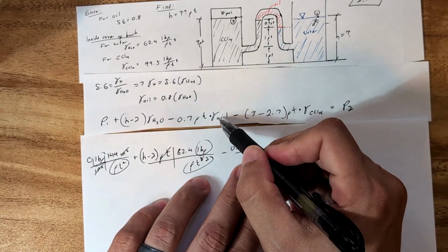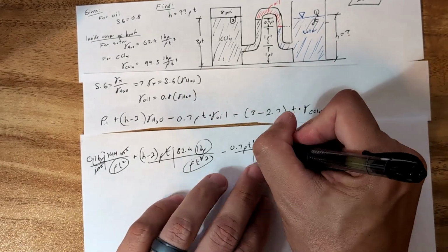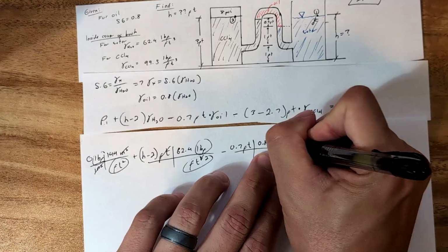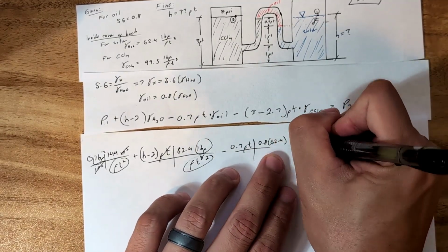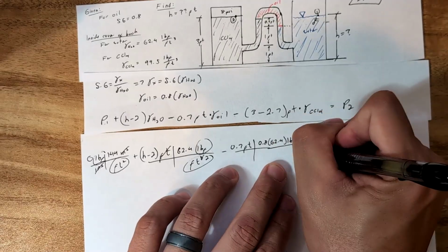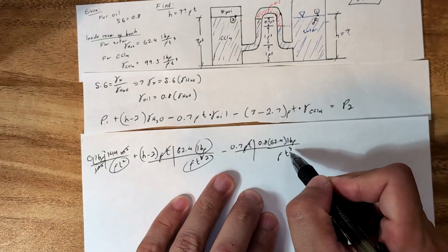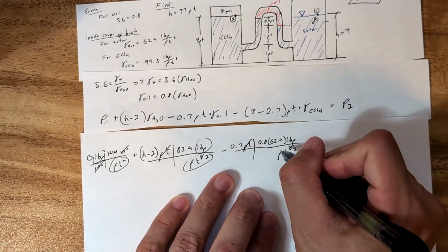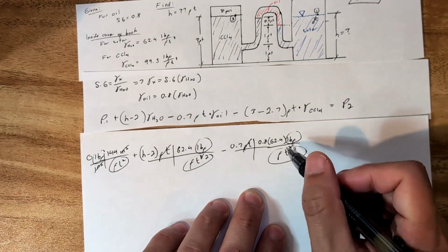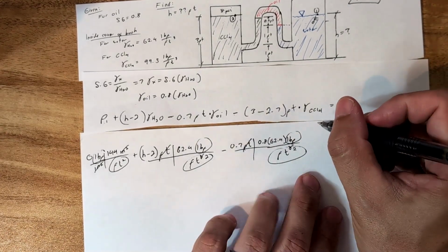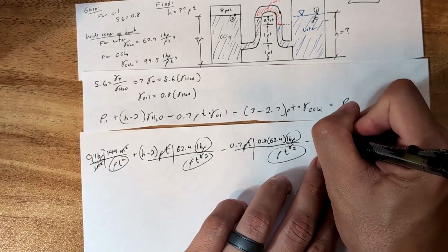And then for oil, we did our bookkeeping earlier, is 0.8 times the specific weight of water, which is 62.4 pound force per cubic feet. And this is going to cancel with one of these feet, leaving this to be foot squared. So we have pound force, foot squared. Perfect. Minus 3 minus 2.7